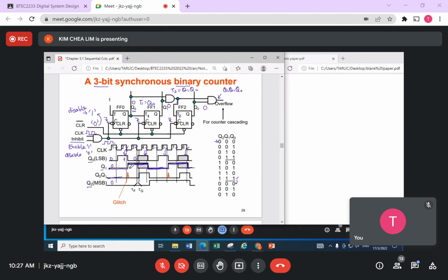And because of some small delay here, although we say that this is 10 nanoseconds, this is another 10 nanoseconds, and so on, it seems like there is no delay and the timing is the same. But this one reacts first, this one will react later. Say, for example, this one delay time here is 10 nanoseconds later, but this part before, it goes up, it can be faster or slower.